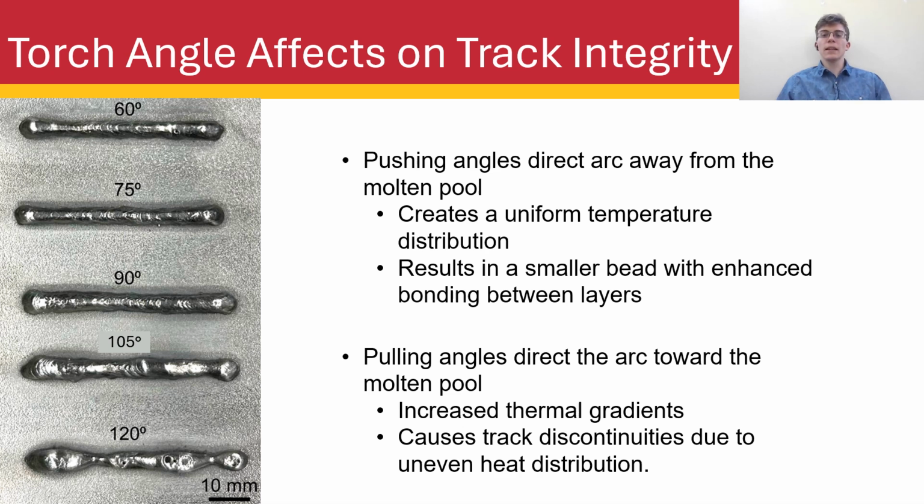The pushing technique, in this case 60 degrees and 75-degree angles, directs the arc away from the molten pool. This promotes a broader heat-affected zone and uniform temperature distribution, which results in a narrower and shallower bead, creating enhanced bonding between layers. This is favorable for most applications.